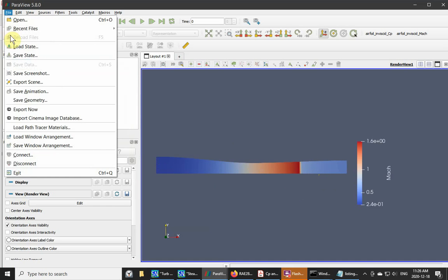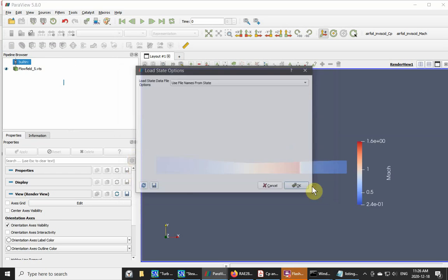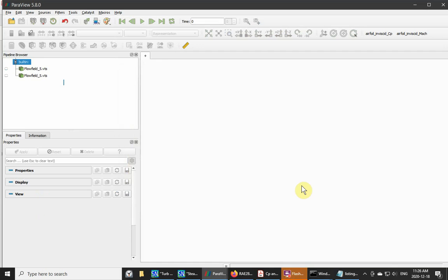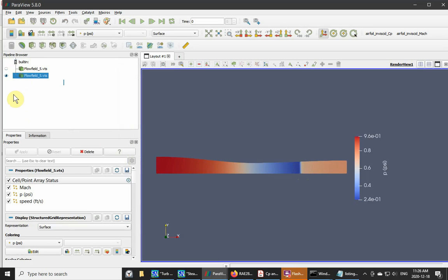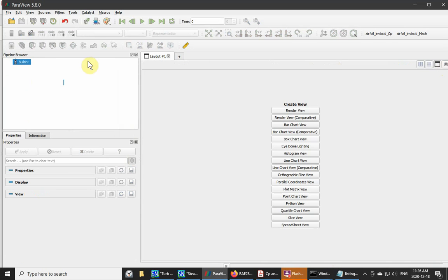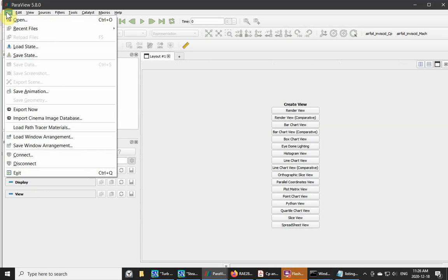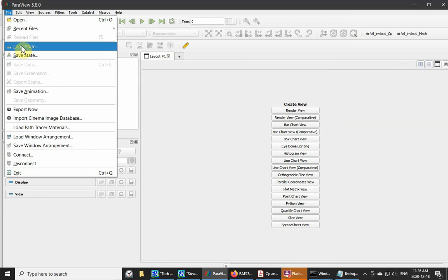And the pressure contours. In this case, you're seeing a high pressure being reduced to quite a low pressure value, and then being increased slightly by the attached shock. Okay, now I'm going to show you the final results, which are for inviscid steady and unsteady flow. I'll load that state.